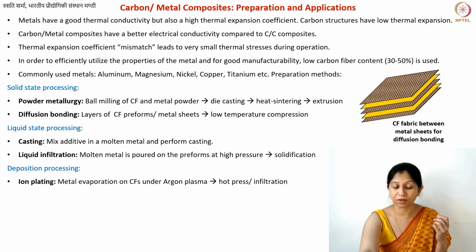So you evaporate a metal at lower pressures or higher temperatures. These kinds of techniques are actually rather common also in microfabrication, evaporation and sputtering techniques. Often they are enhanced, supported with plasma, for at least a little bit of impregnation of the ions. This is why it is known as ion plating. So you're doing plating, but you want a very good adhesion. Not impregnation in the same way that you do doping or anything. No, that's not your goal.